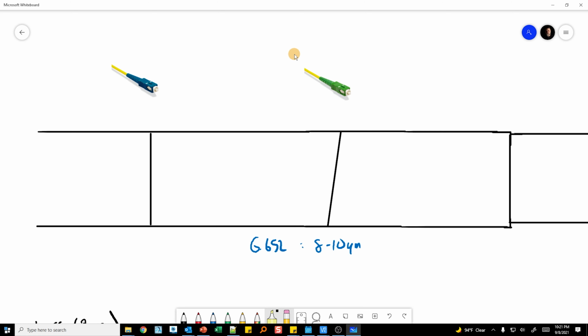But essentially, what we do is we inject light at a specific angle, and it reflects off of the cladding. This middle section here is the fiber, and wrapped around this is the cladding. This is all the cladding. Again, I say wrapped, but it's really melted together. The cladding has different optical properties, a different index of refraction, and so it maintains the signal within the core, and it also protects the core. Those are some of the functions of the cladding.